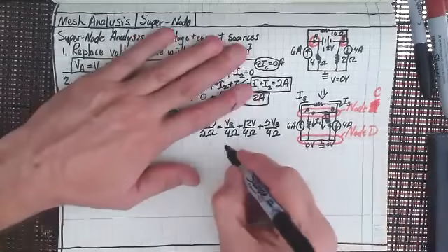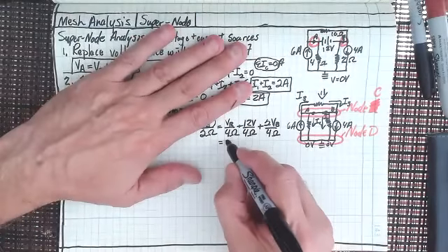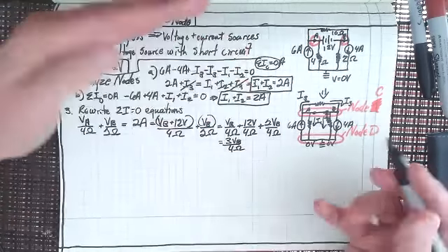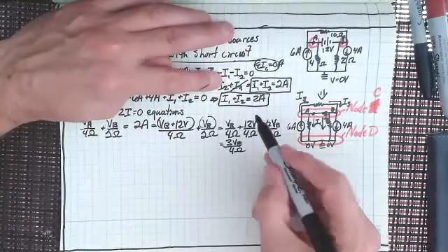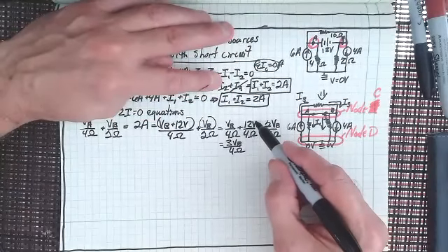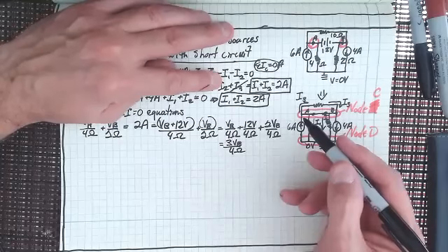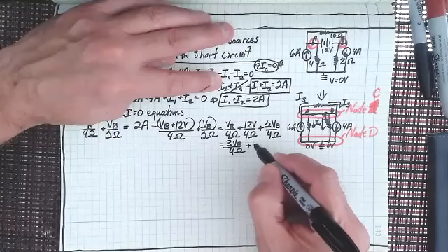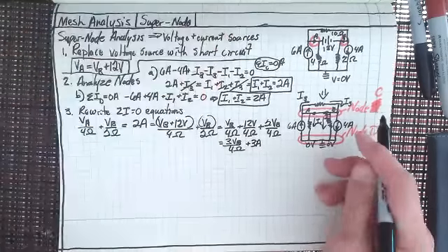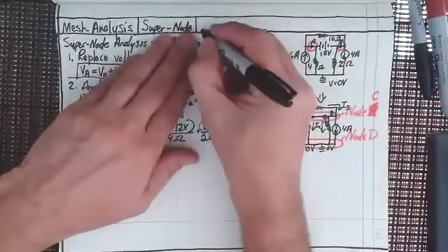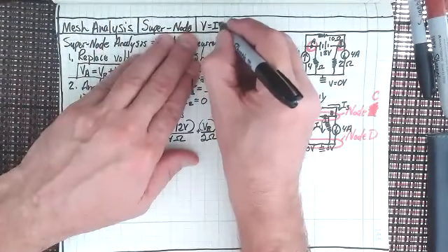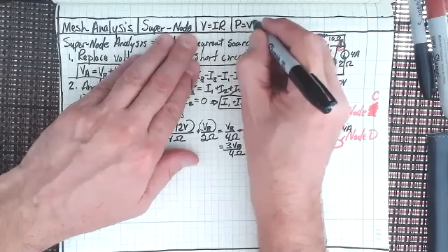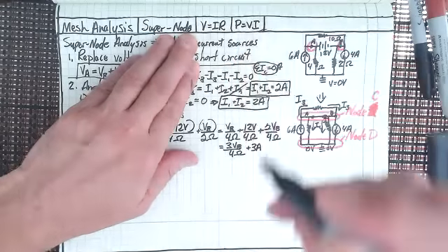And then let's look at this. Let's just rewrite this out. So 3 V sub B over 4 ohms. I don't want to take up too much room. And then I have 12 volts over 4 ohms. So that's going to give me a current, isn't it? That'll give me plus 3 amps, right? V equals IR. Let's never forget that. V equals IR. P equals VI, right?